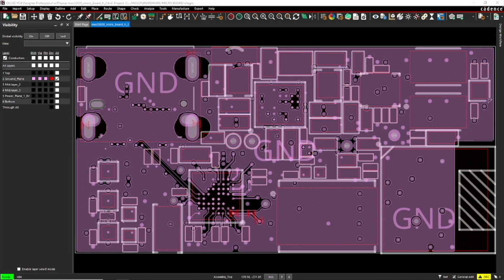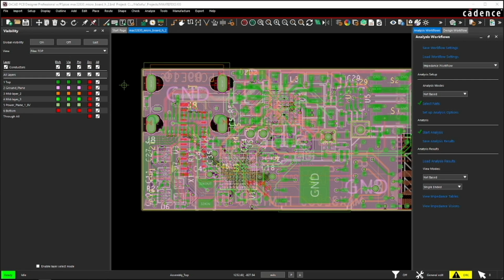The designer tried as much as possible to avoid routing traces through the ground plane. For every design with a ground plane, avoid touching or breaking up the plane as much as possible. This is to ensure minimum return path discontinuities, since it's a critical voltage reference for all components and signals. Let's analyze the impedance throughout traces in the design.